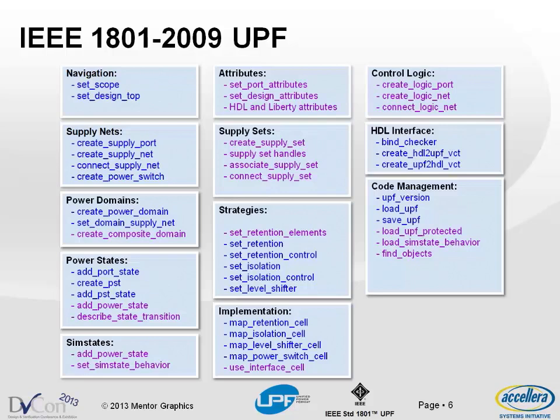And this is referred to as UPF 2.0. So chief among the new additions is this notion of supply sets. We'll talk more about what supply sets are, but this is the central change from the Accelera standard to the IEEE standard. It's a more abstract model for how you represent the supplies that are provided to different power domains, to different cells in the design. And it enables a lot of the other capabilities in IEEE UPF.